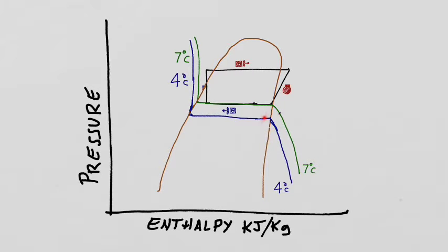This lower pressure temperature will create a higher heat of compression. That is, the work the compressor does to lift the low pressure temperature refrigerant to a high pressure temperature state where we are going to condense and reject the heat.